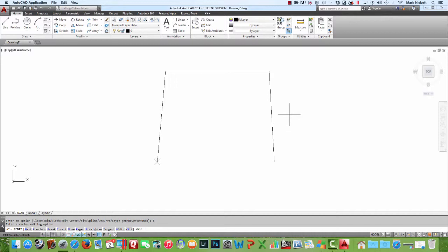This time we're going to go up to this segment here and insert a new vertex point, because occasionally you may want to put in another vertex point, like we want to come down and then go back up. So I can say I for insert, and then specify where I want to insert the next point, and it'll put that point in, and then I can either go to the next point or get done and hit exit.